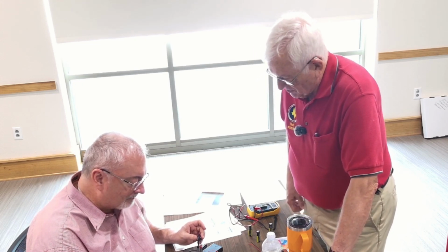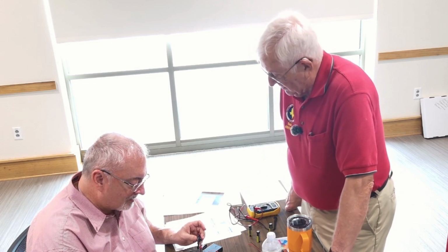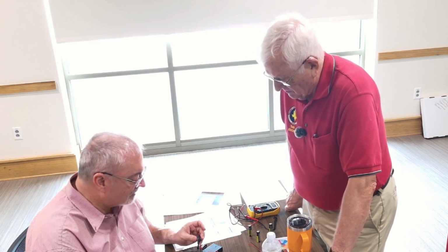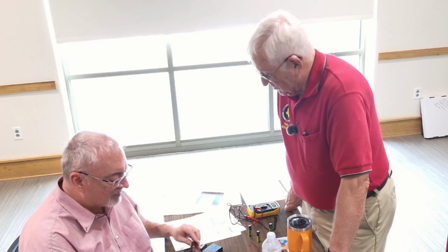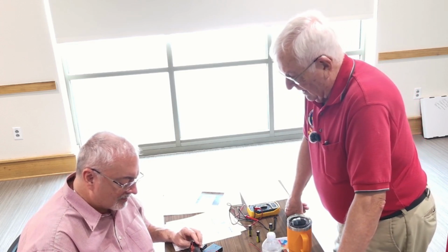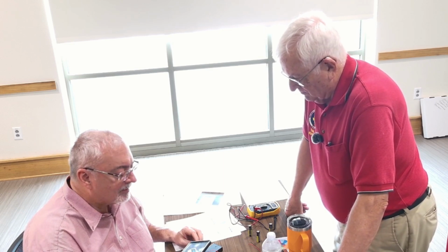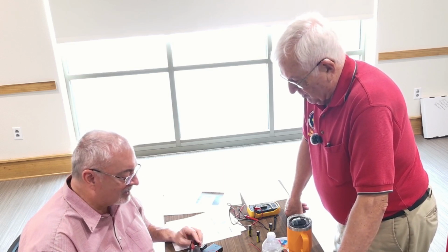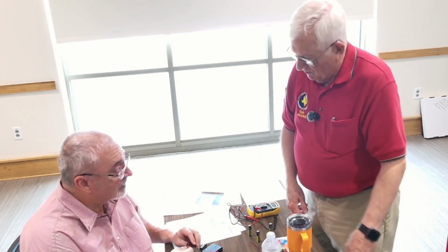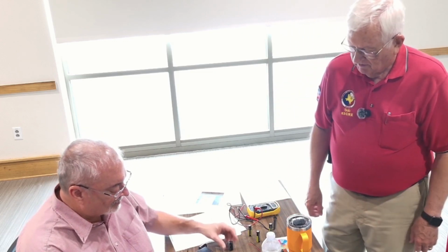This does resistance, capacitors, and inductors, and it'll read down into the microhenries, 1 or 2 microhenries, very easily. And likewise, resistors, if you have real high tolerance resistors, it'll measure those down and give you a really good read. Those work, and they just work. These other meters, you got to set the range and mess with them and all that. This, you just push the button. So I use that one all the time. I love that one. It just works.